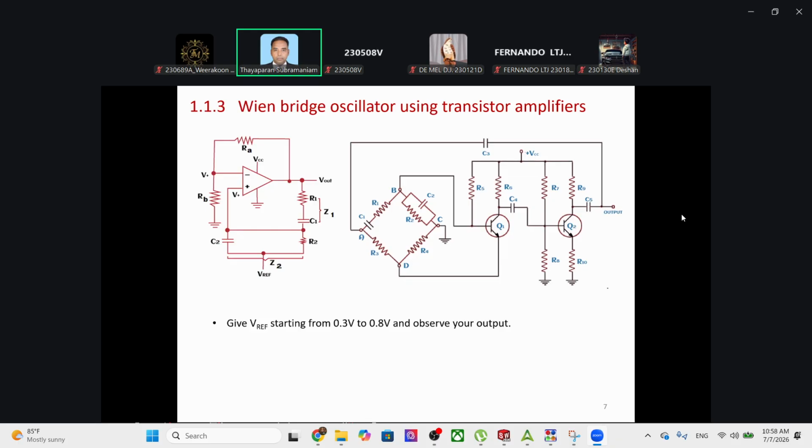So how do you make sure? You connect a series resistance here, measure the voltage across the series resistance and see how much current is flowing through that resistor. Or you can observe the waveform using an oscilloscope. But anyway, it is not for the lab.